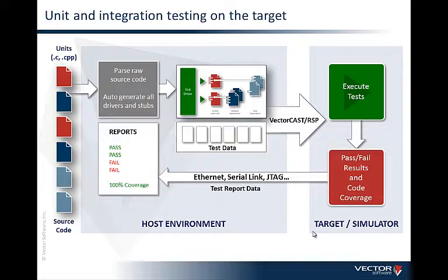So our unit test schematic for downloading onto the target, executing and bringing back the results might look something like this. In the example we will look at in the following part of the presentation, the GDB client will connect to a GDB server, which will connect in turn to the JTAG controller, which will connect to the board.